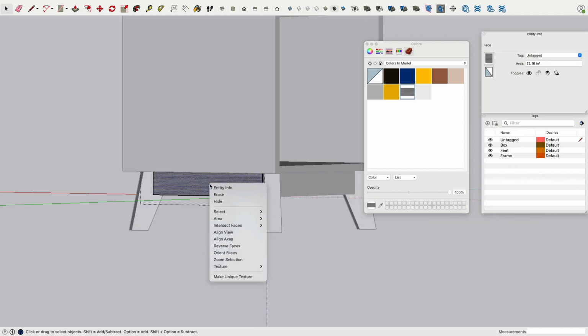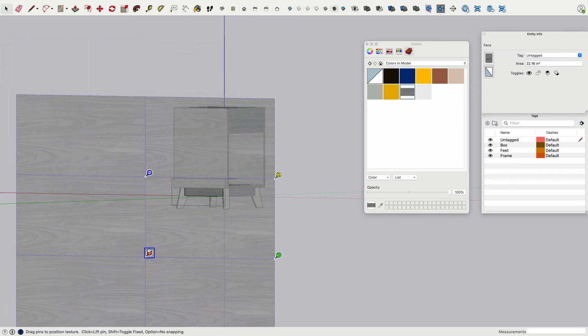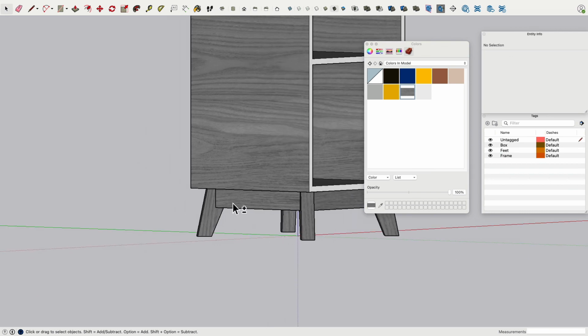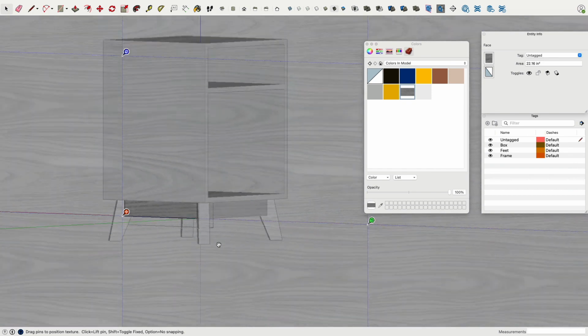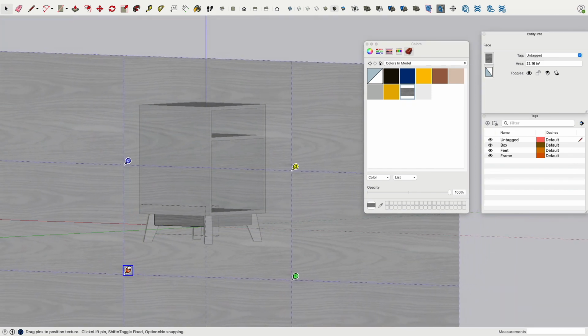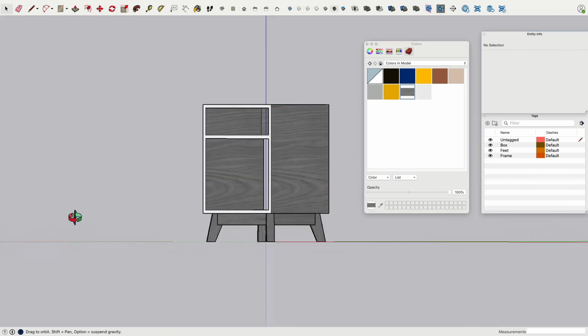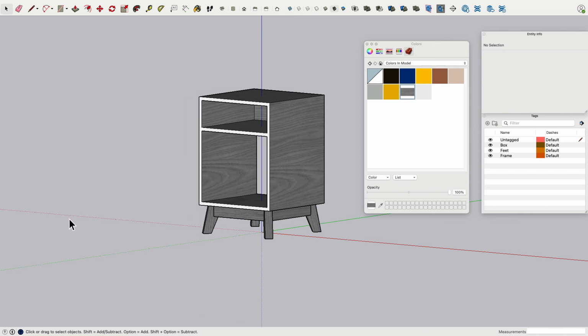And then here I will use maybe an area up there of that image, and here I will use another area of the image. And then this way, when I use the same image as a texture, I randomize actually the parts I use, and this way create really a believable impression that each piece is really an individual wood element.